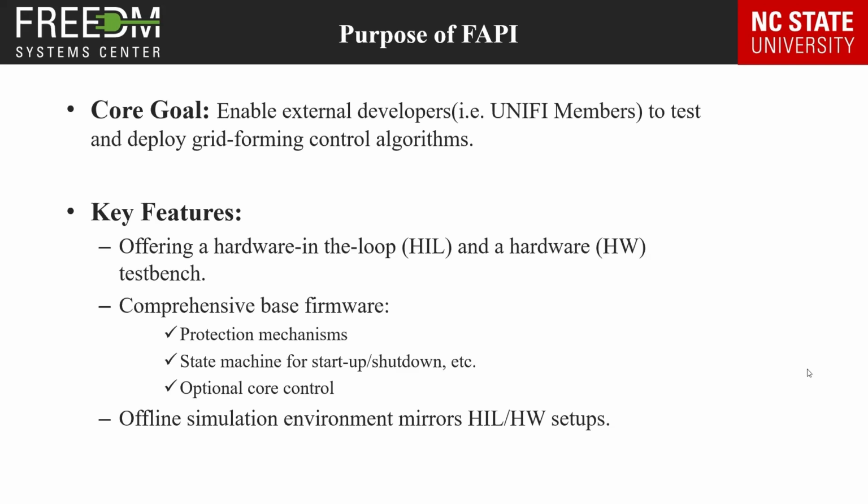This serves both for the validation and implementation of the NCSU grid forming controller with fault ride-through features, as well as for enabling other UNIFI members to implement and validate their code using the NCSU TI DSP based HIL and VSI hardware. As the name implies, the test setup already has a comprehensive base firmware that includes protection, state machine for handling startup, shutdown, etc., and optional core control.